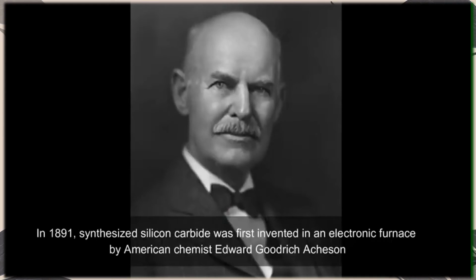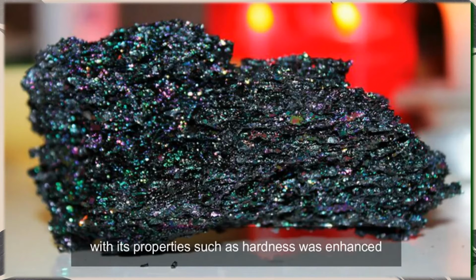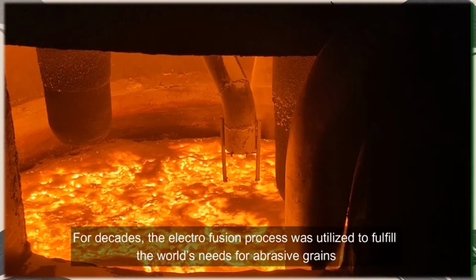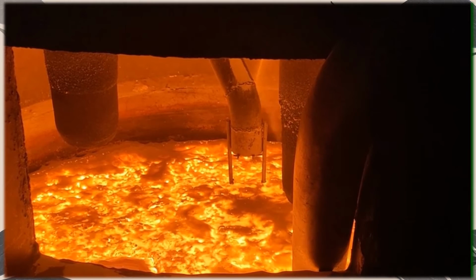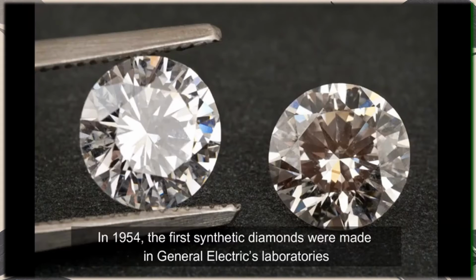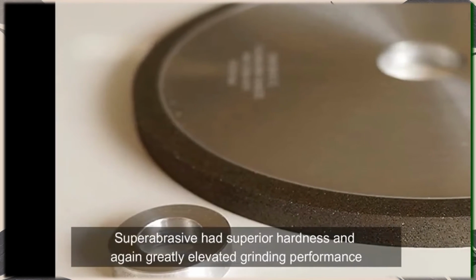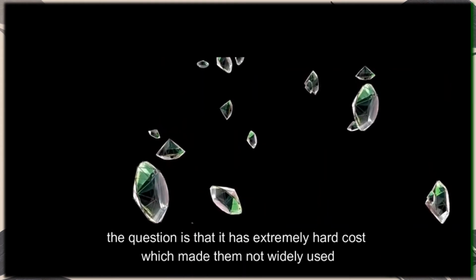In 1891, synthesized silicon carbide was first invented in an electric furnace by American chemist Edward Goodrich Acheson, with properties such as hardness enhanced. Following the development of silicon carbide, synthetically manufactured fused alumina was invented. For decades, the electrofusion process was utilized to fulfill the world's needs for abrasive grains. In 1954, the first synthetic diamonds were made in General Electric's laboratories, which revolutionized the industry and set a milestone of superabrasives. Superabrasives had superior hardness and again greatly elevated grinding performance. The problem is that they have an extremely high cost, which made them not widely used.